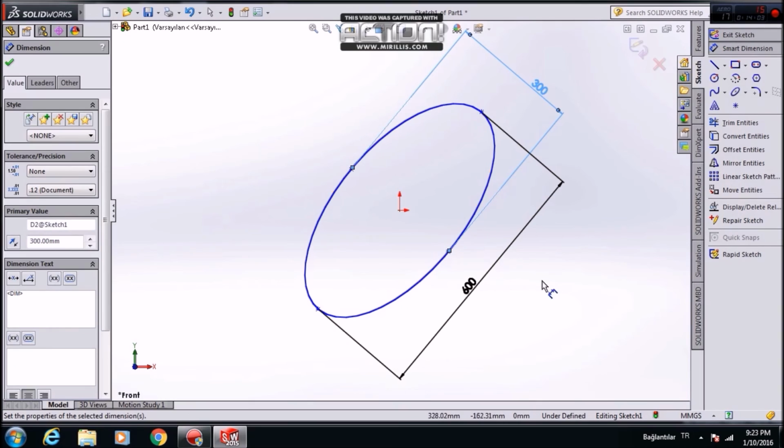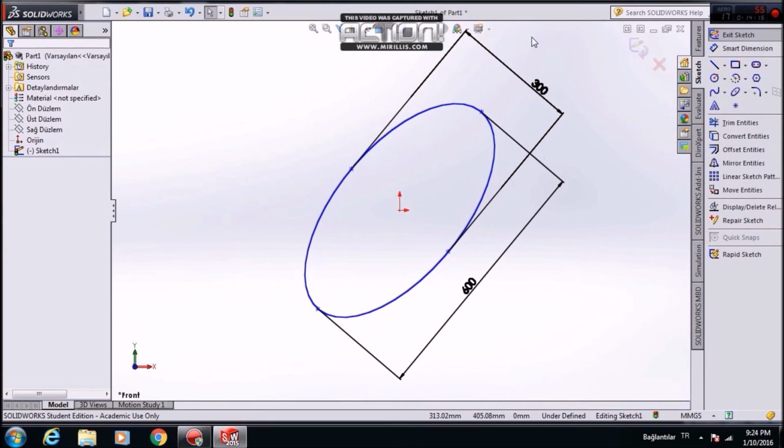When we do this, on the left window, there will show up some major geometric constraints. Of course, when we do this, we can understand that even if we have assigned the lengths, still our sketch is underdefined. In order to make the sketch fully defined, we are going to assign more geometric constraints. For example, we can assign that these 2 points are horizontal. That is, they lie on a horizontal line.